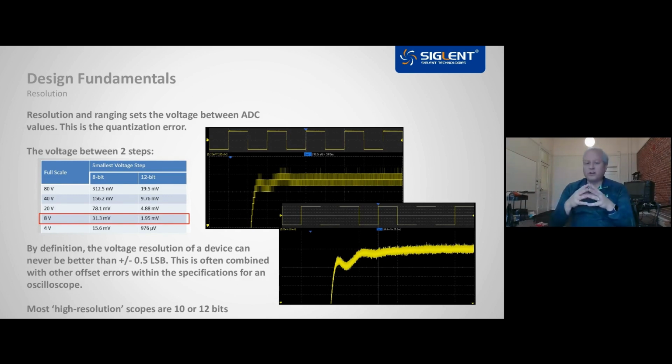So with resolution, there are lots of different ways to talk about resolution, filtering, and averaging. These are all really interrelated, so companies talk about these in slightly different ways. What's most important to start with is true resolution. True resolution is equivalent to the number of bits captured by the A to D for each sample. Additional bits of resolution are often discussed as part of an ENOB or as a result of filtering, but we need to start with the true resolution of that A to D.